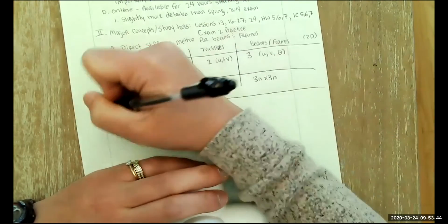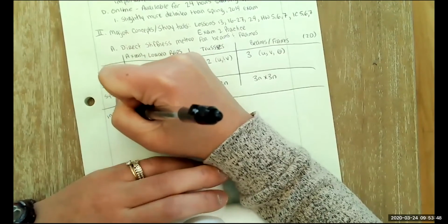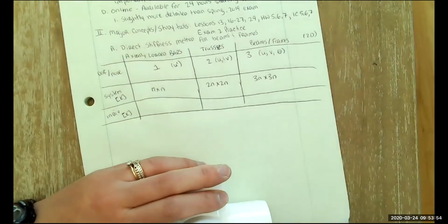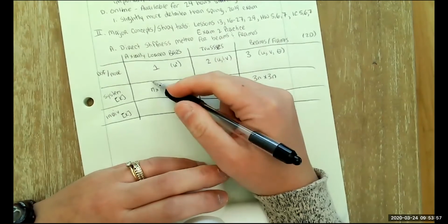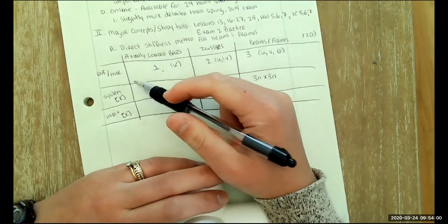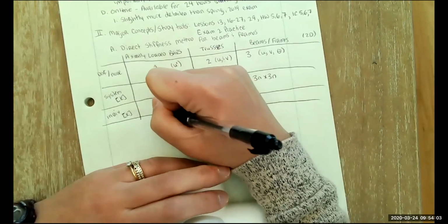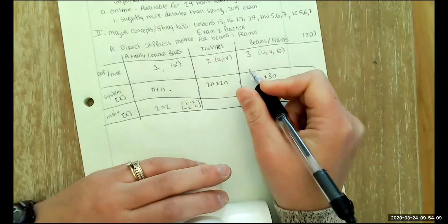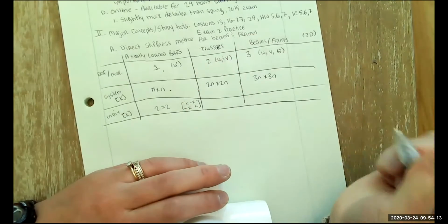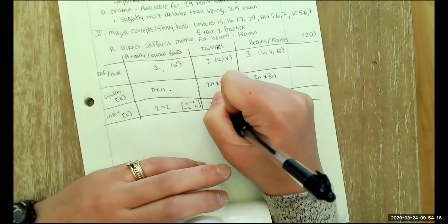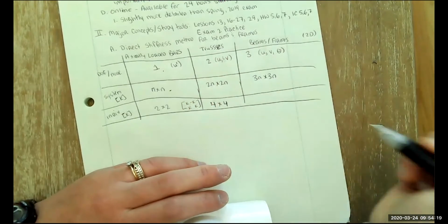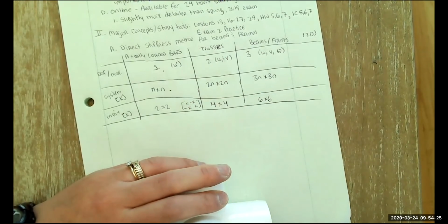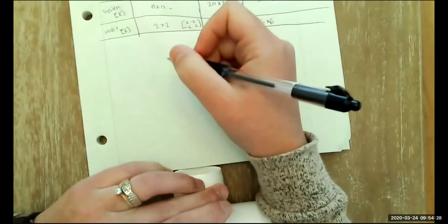Similarly, our individual stiffness matrix. Sorry for the wave there. Again, for our individual stiffness matrix here, I have 1 degree of freedom at each node, 2 nodes per bar, so it'll be 2 by 2. Remember, this is our K, negative K, negative K, K. For a truss, we have 2 degrees of freedom at each node, 2 nodes per bar. 2 times 2 is 4 by 4. So for beams and frames, that individual stiffness matrix is going to be 6 by 6 for every single bar that I have. So how many individual stiffness matrices do we need?